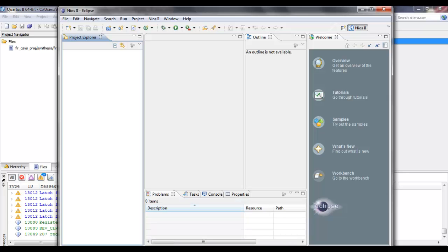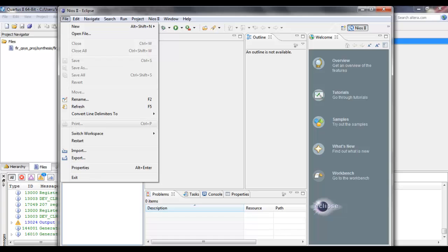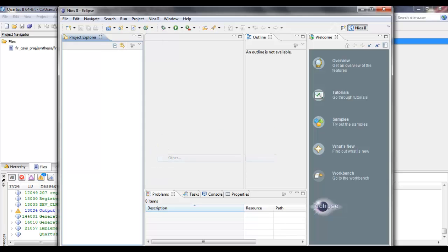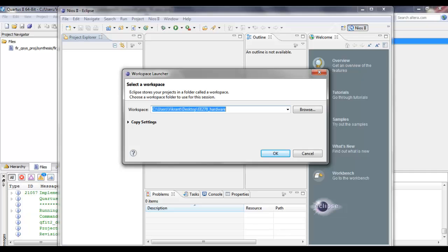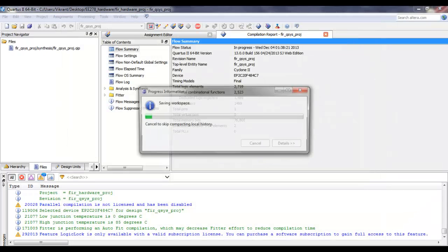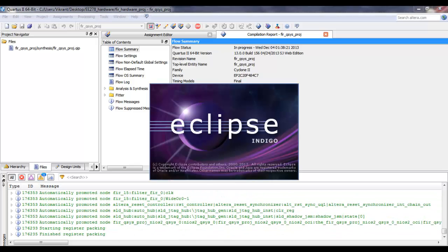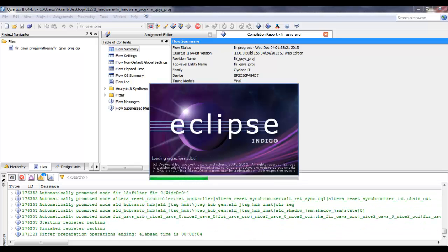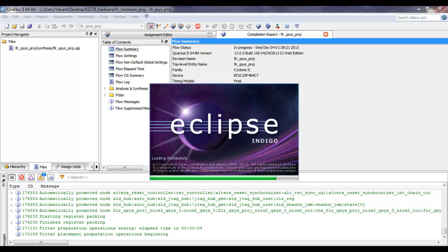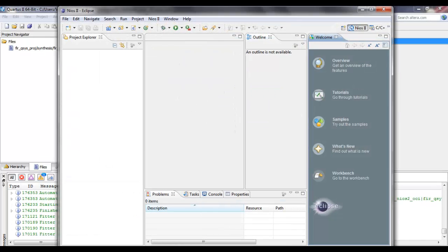Initially I was getting errors here because my work directory was different, but having done it a repeated number of times, I eventually got to know that the work directory has to be the same. The simultaneous compilation in Quartus will produce a SOF file which will represent the system. Now this file will be put in the DE1 board.